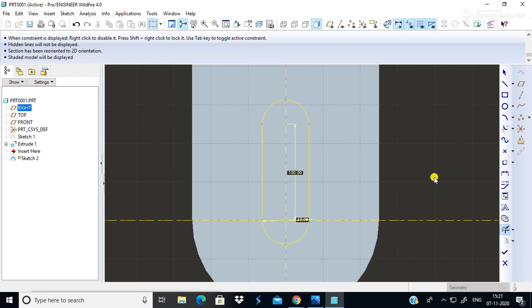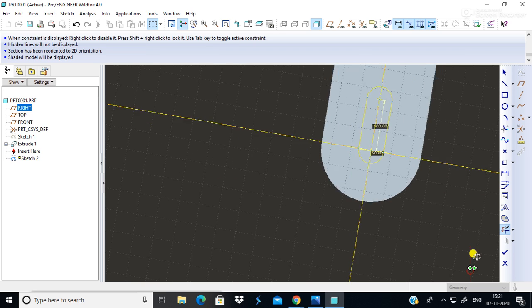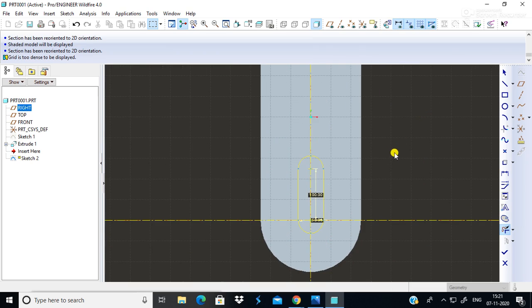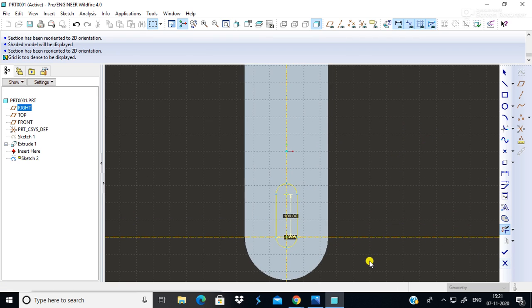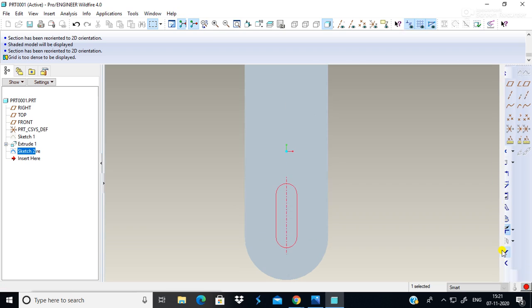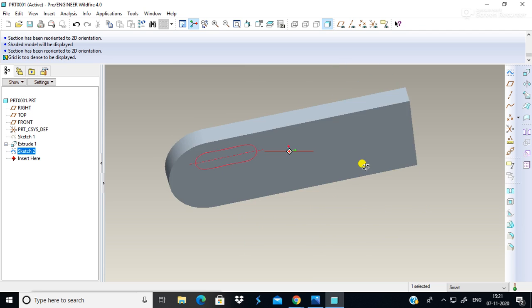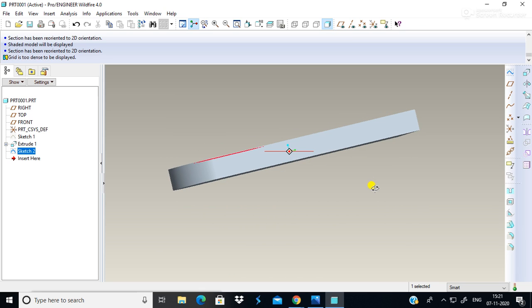This is the feature you have drawn. Again we re-enter the sketcher module, because you forgot to draw that feature on your base feature. Now we will exit from the sketch mode. Now this is a newly drawn sketch on your extruded feature. You can see that when I am looking from the side view, it is drawn on this plane, not on the bottom plane.